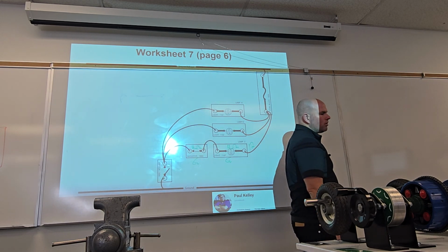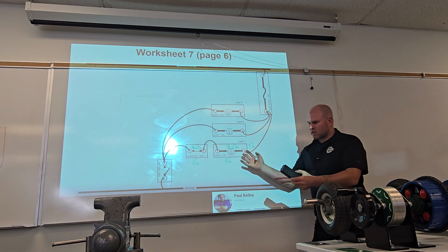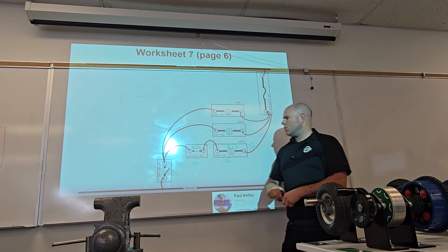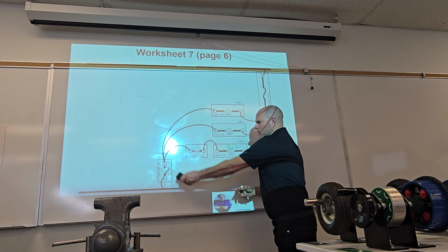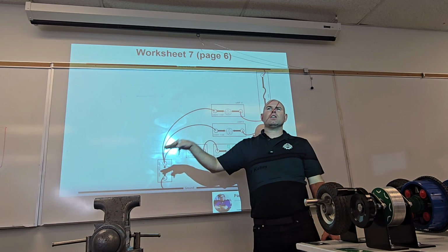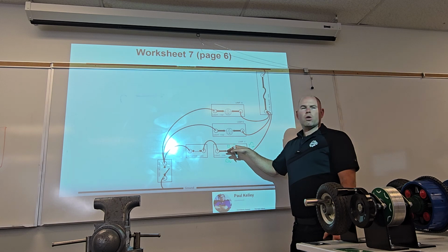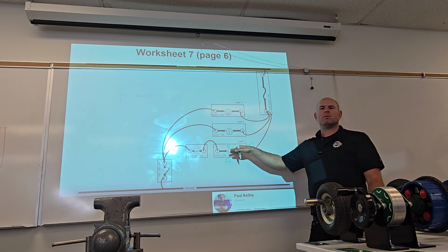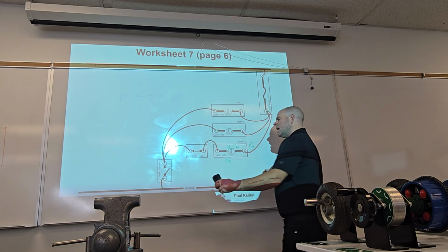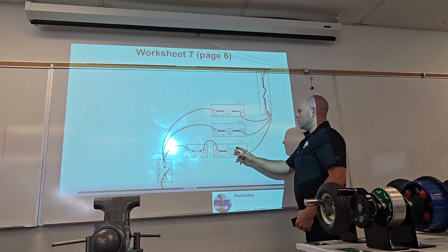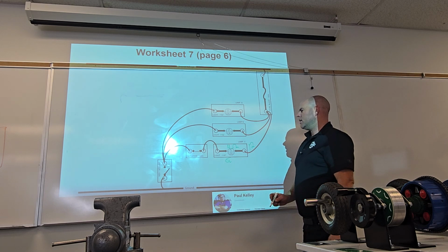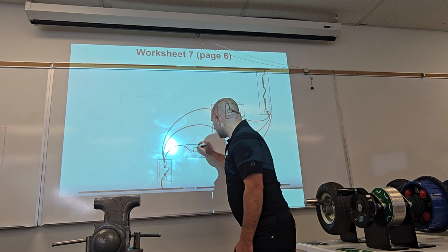Now in practical, this is the theory. If it's on the car, the likeliness of you having not a resistor, but a corroded connector, and it being exactly 4 ohms on the corroded connector, the same as the load, is probably not likely. Let's just say you had 4 ohms here, and you had, how about 2 ohms right here?